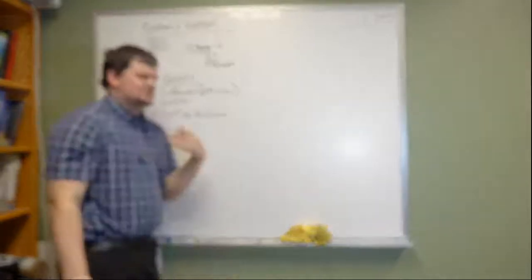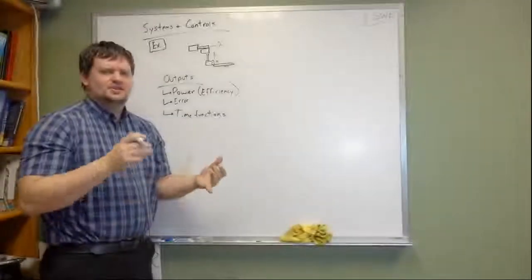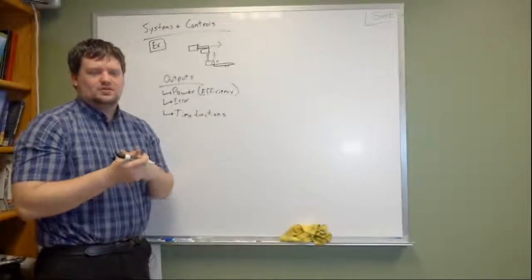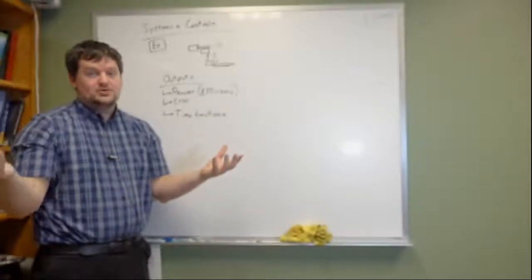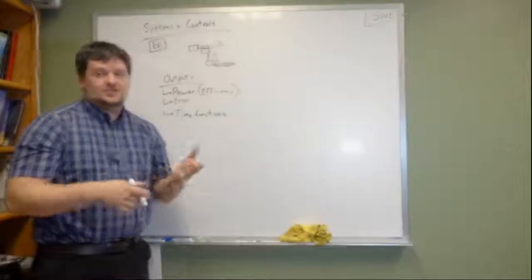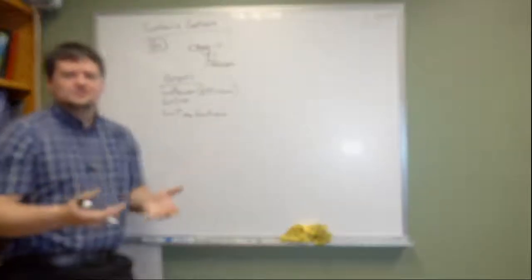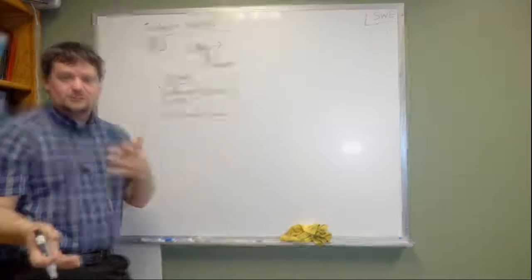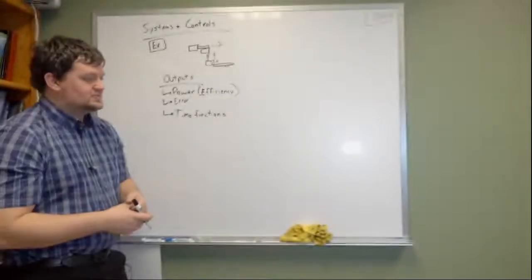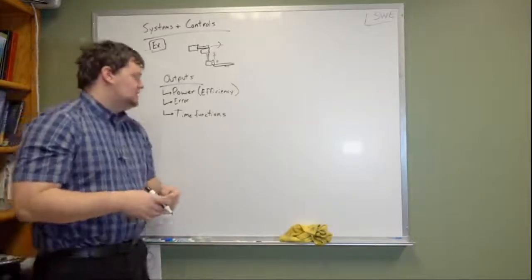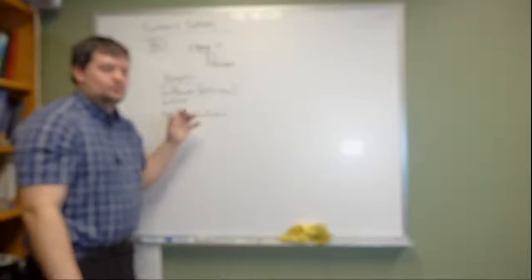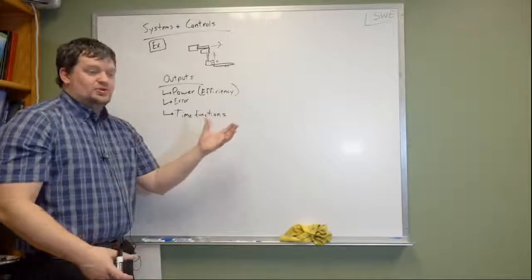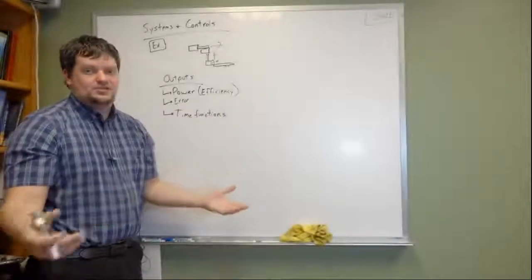because every single component has some element of a capacitive component, an inertial component, and a resistive component. We talked about real systems. Real systems have all three of those present: capacitive, inertial, and resistive, or dissipative, components. And that's going to affect how the time function works for that item. How does the input get to the output, how much time does it take for that to occur?